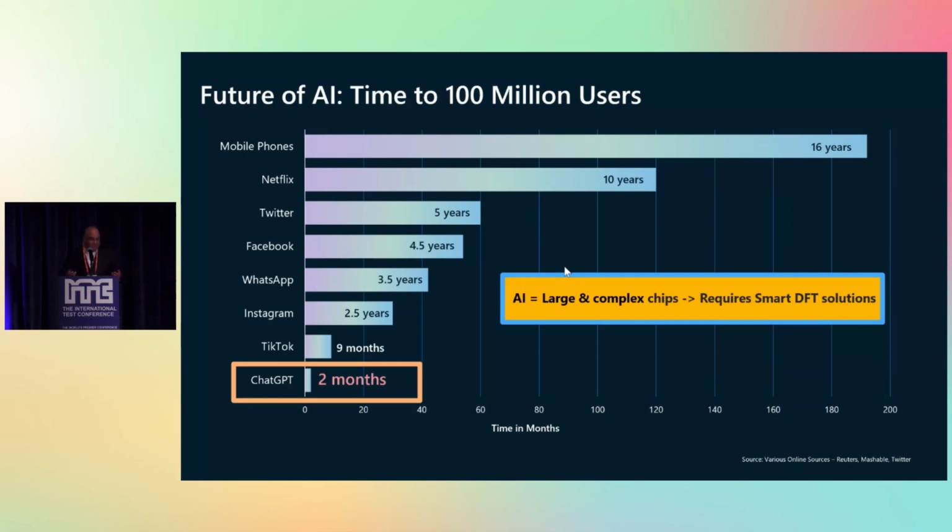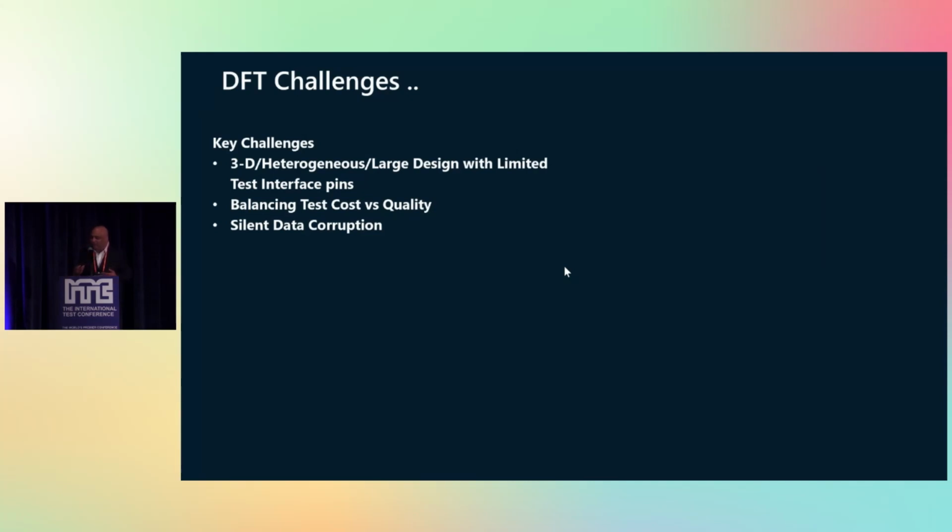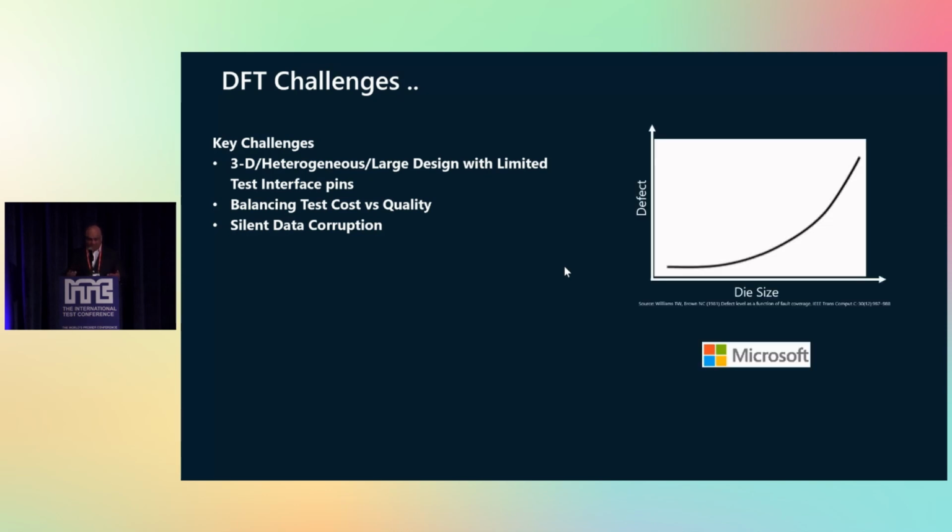Okay, so I'm going to move on. I'm just going to continue with the industry trend, and talk about what challenges we are seeing in DFT. Obviously, the whole theme of the conference today is heterogeneous integration, 3D. And that's one of the biggest challenges we see as a DFT engineer. You have limited pins. You're not able to access all layers of the chip.